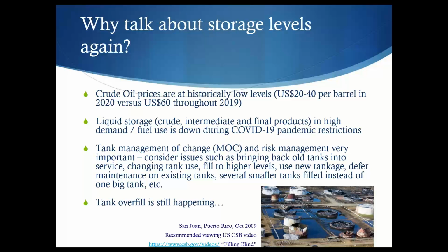In their case, they had an overflow of around 200,000 US gallons, which is somewhere around 760,000 litres. It was detected and the transfer was stopped, but by the time it was stopped, the bund drain valve was left open, so the liquid that had spilled over into the bund had gone down the drain. It flowed from the bund, reached the waste treatment plant and was ignited by an unrated piece of equipment in the waste treatment plant. It caused the flame front to burn back to the bund, causing an explosion, and the resulting explosion was around 2.9 on the Richter scale, so a pretty large bang.